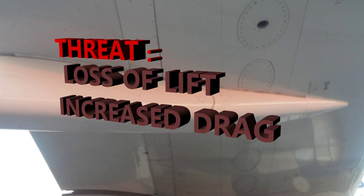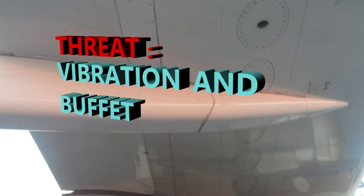And again, that shock wave is created, so it creates this separation, and the aircraft doesn't have the leverage, if you will, to continue to have the lift that's necessary. Remember I said it increases the drag. So it's just much more difficult at that point for the aircraft to stay lifted up in the air. Vibration and buffet are also another threat to the aircraft.